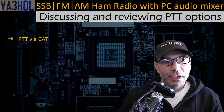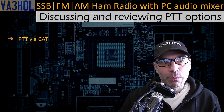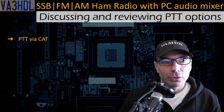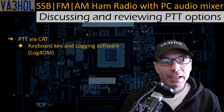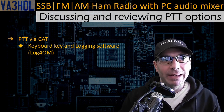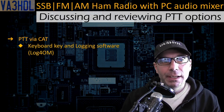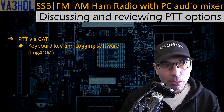So what are the options that we have for push-to-talk to put the radio into transmission mode? The first option is to do that via the CAT commands. That is very simple. It can be achieved in two ways. One way is using a keyboard key programmed in your logging software. In my case, I am using Log4OM. I highly recommend that logging software. I can program any key on my keyboard that I want to use to put the radio into transmission mode.